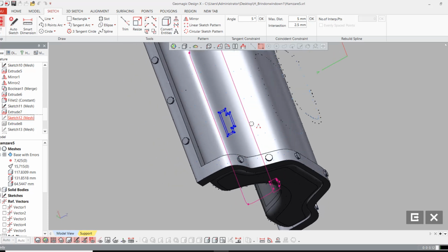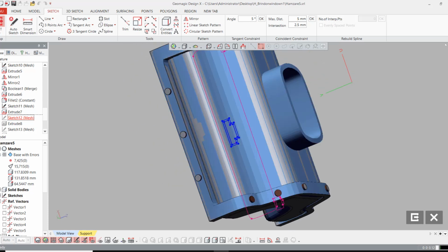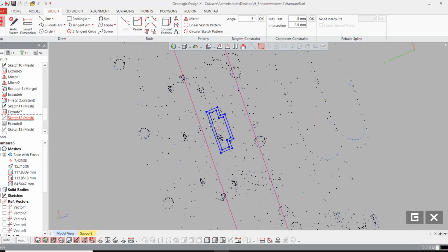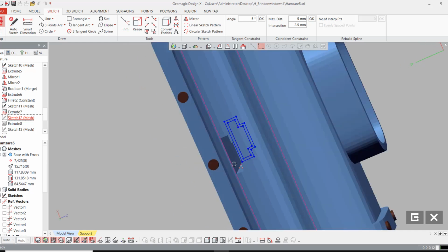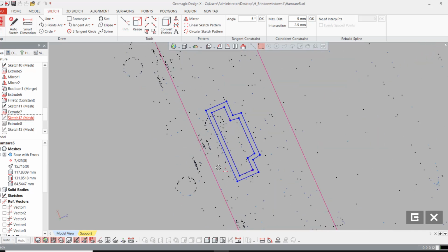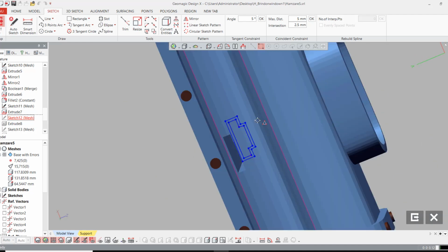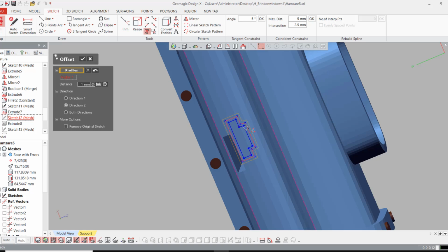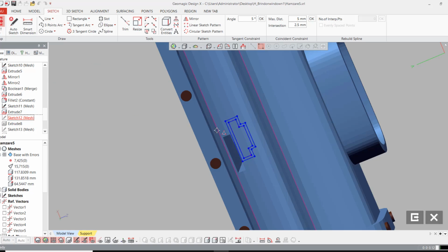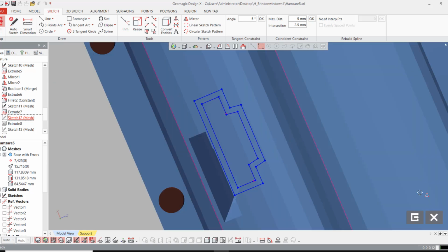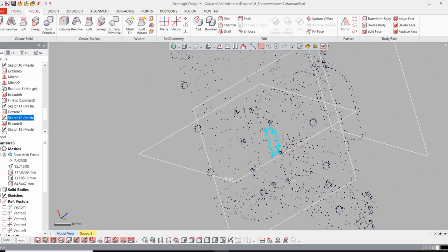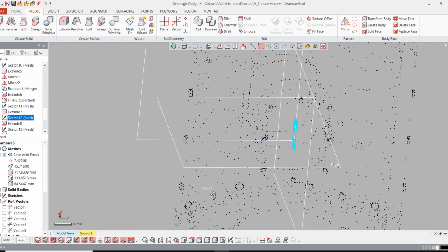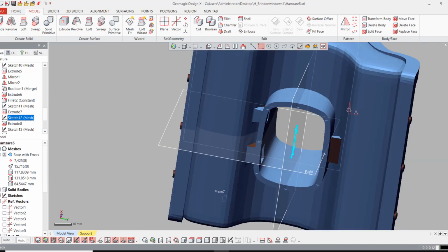We will use this mesh to create this mesh section sketch, and this will capture the detail of this cut, and then we can offset this by using this offset command. We can offset, and then we will extrude only this middle portion, and we will extrude it up to this inside surface.